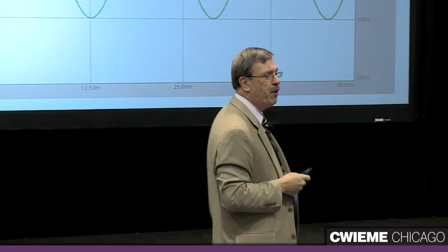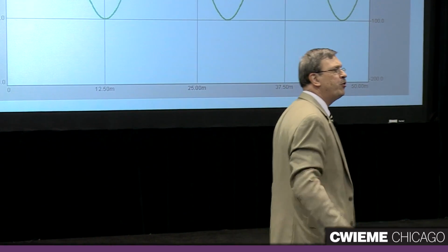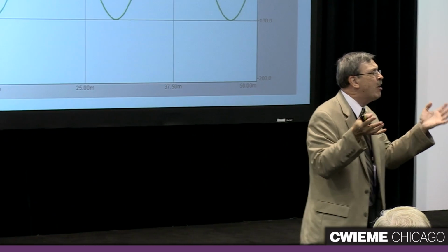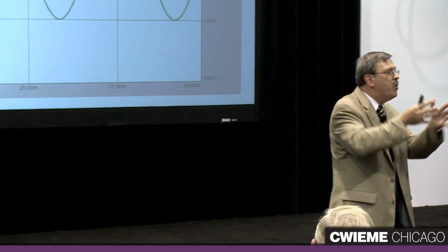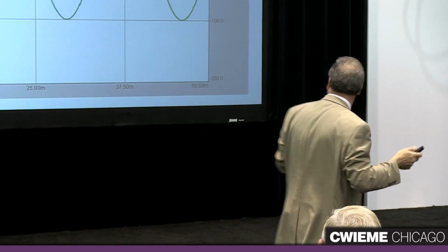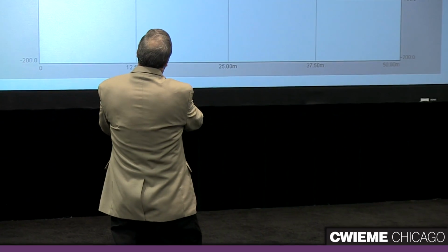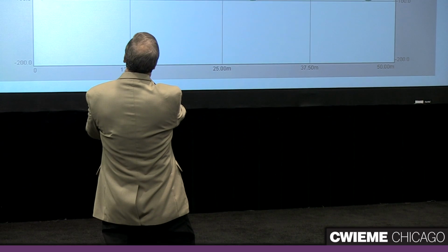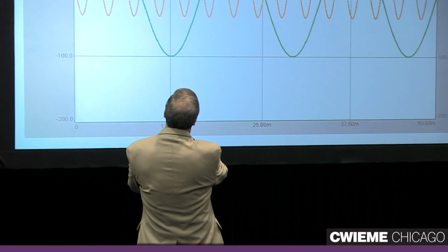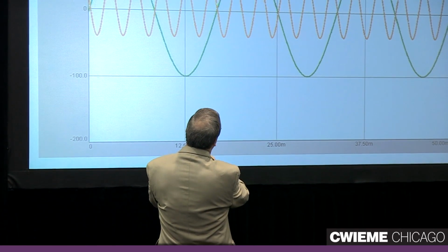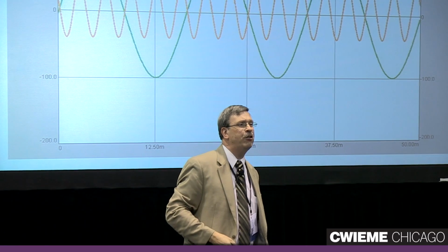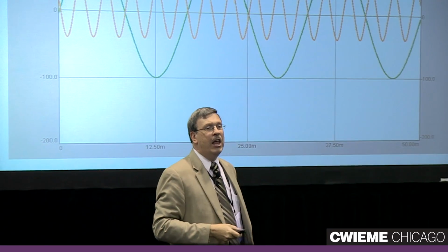I'll show you what a fifth harmonic looks like. Here's a fifth harmonic. You might wonder, how do I know it's a fifth harmonic? All we have to do is count how many cycles there are within one full cycle of that fundamental. If we start right here, one cycle of the fundamental goes from here to here. So if we start right there, we go 1, 2, 3, 4, 5. There's actually 5 cycles of that, so we know it's a fifth harmonic.